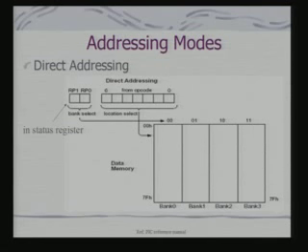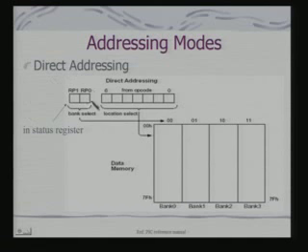Now let's look at addressing modes. What is addressing mode? We use addressing mode for specifying operands in an instruction. PIC supports direct addressing, indirect addressing, as well as immediate mode addressing. We have already seen the structure of instructions which support immediate mode addressing.